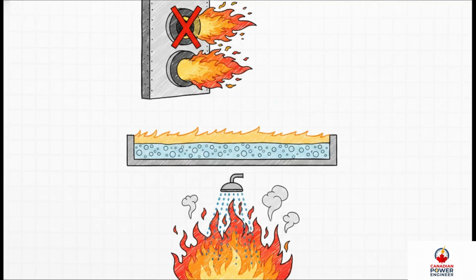Beyond the actual structural design of the plant, you also have some temporary operator tricks up your sleeve. When your load permits, taking your highest top burners out of service while leaving their air registers wide open forces the lower burners into a fuel-rich state. That one simple manual move can cut NOx by up to 20%. Other methods include utilizing fluidized bed combustion, since it naturally operates at lower temperatures, or even injecting water or steam directly into the combustion zone to literally cool the fire down.